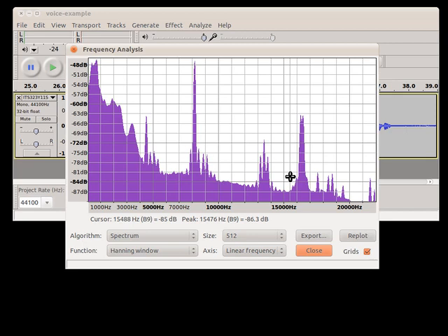The analog signal sent from the wireless transmitter to the receiver is approximately ranging from 670 megahertz to 670.2 megahertz. The 0 to 0.2 means there's a bandwidth of 0.2 megahertz, which is 200 kilohertz. That is, this wireless transmitter transmits a signal with a bandwidth of 200 kilohertz at a frequency of around 670 megahertz. My voice and the original signal had a bandwidth of 20 kilohertz, from 0 up to 20 kilohertz, maybe centered on about 10 kilohertz.